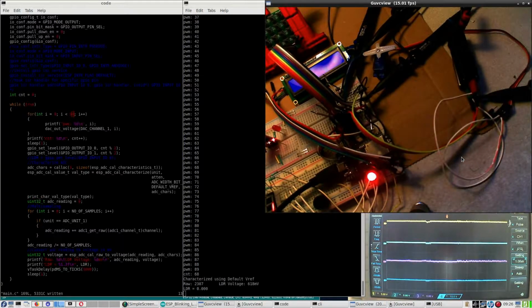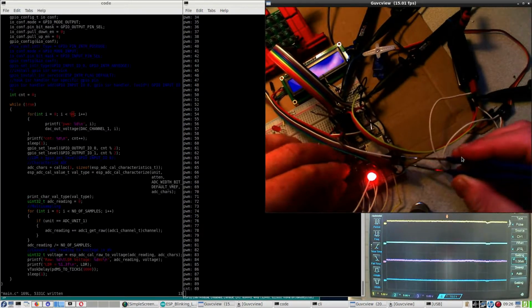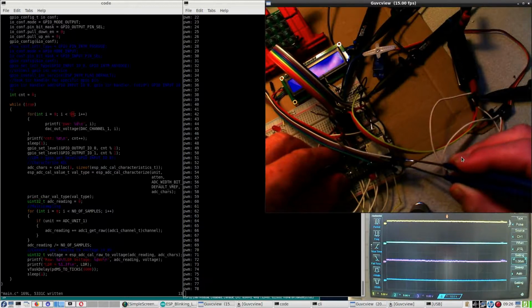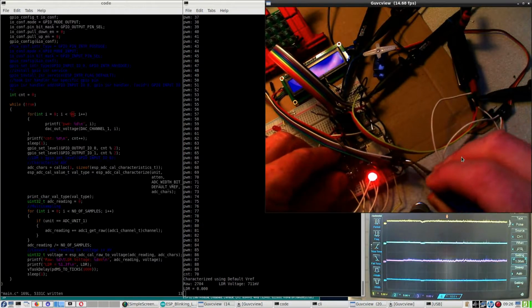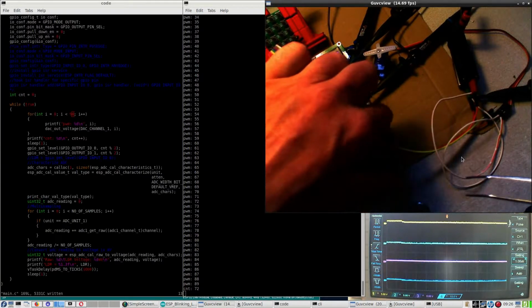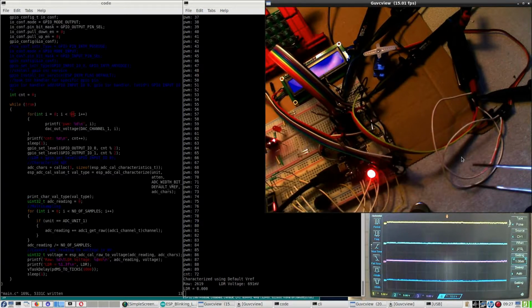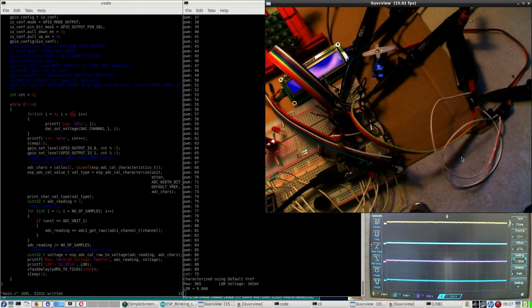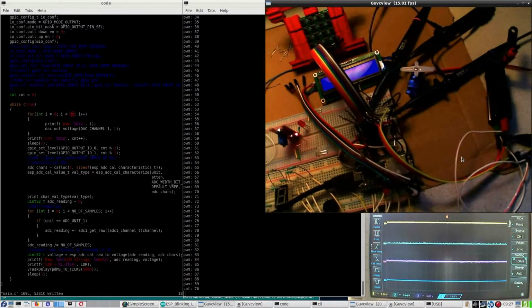And one other thing I noticed is that the main here isn't properly seated. Now it is. This should be properly seated as well, but it looks like it is. No, it's 0. Absolutely 0. I think I found a problem in the wiring, why the motors don't work anymore. I'll have to check that out.